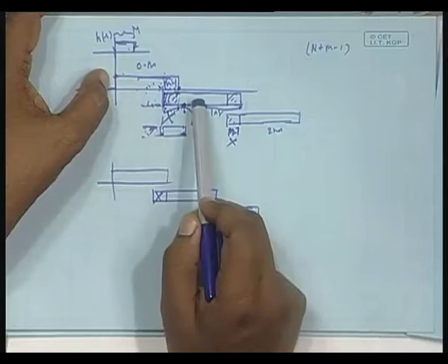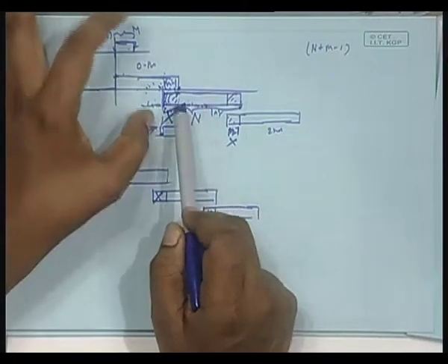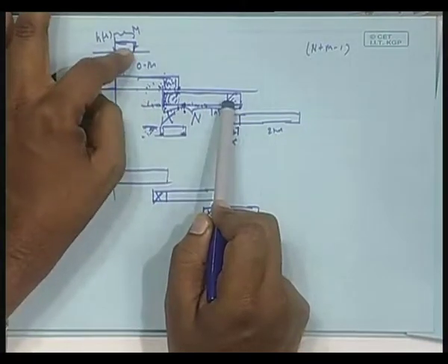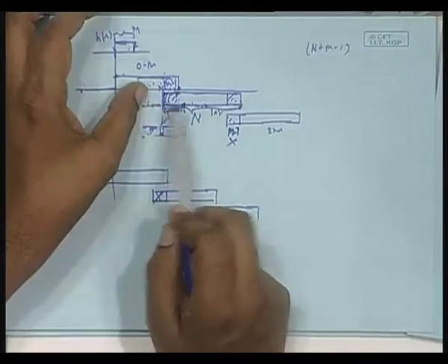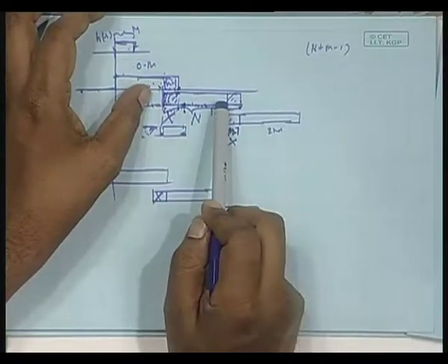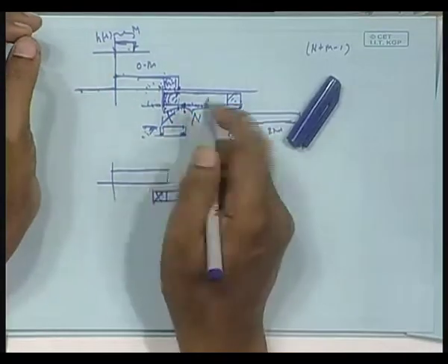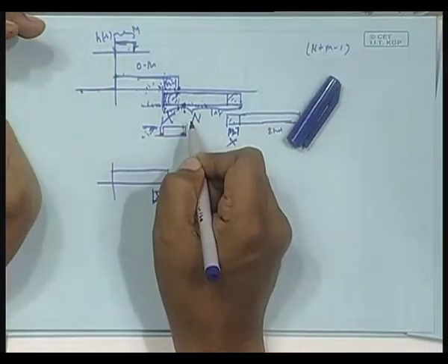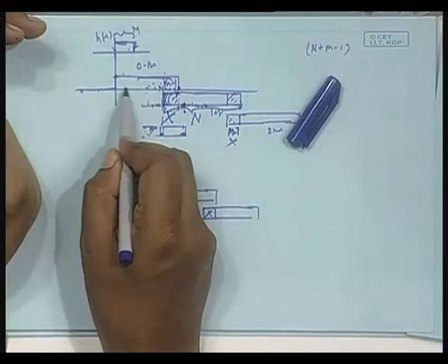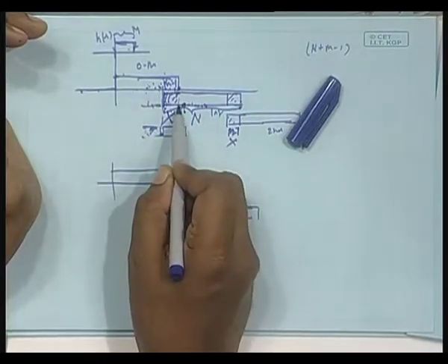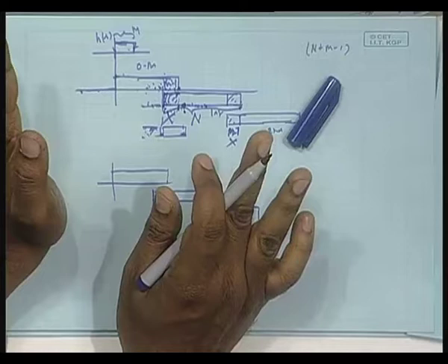So, you understand how it will be used in the adaptive filter case, not weight updating I am talking of now, I am only talking of the filtering part. For this block, one set of filter weights, for this block another set of filter weights, but for this block, say this is the filter weight, I have to convolve between this and this block. From this point onwards, to get the output, I do not need any data from this block, because the previous m minus 1 samples available here are enough for me.